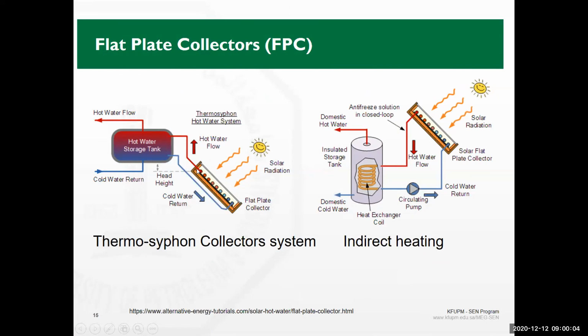The hot water becomes lighter, and on the other hand, there is cold water here, which is heavier. Flow of the cold water here pushes the hot water above, and then you are having some sort of natural circulation here. It is not necessarily water, by the way. You can have special heat transfer oils in here.